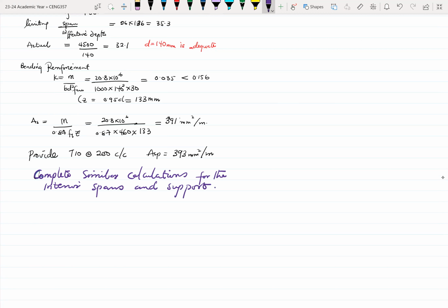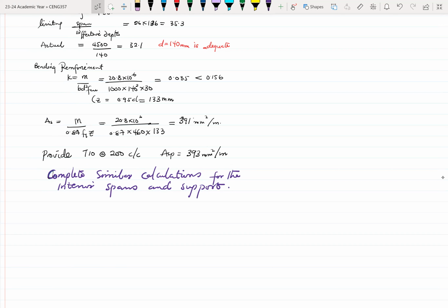When it comes to shear, this is going to pass in the sense that you wouldn't need to check for shear, because V will be less than 0.5 Vc. So no need for shear links. Okay, so this is supposed to be the bending reinforcement or the main reinforcement.